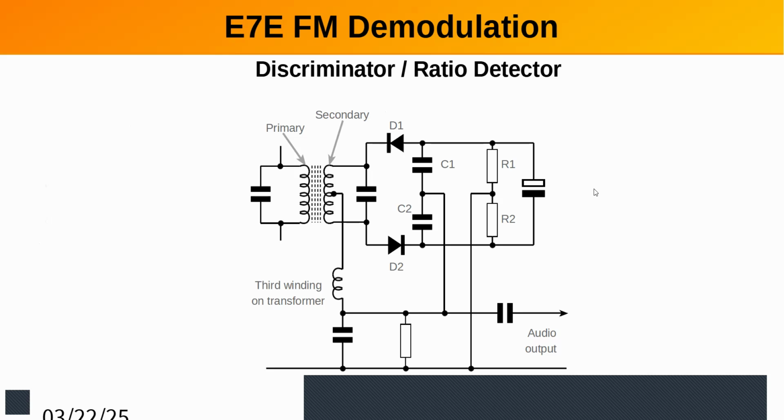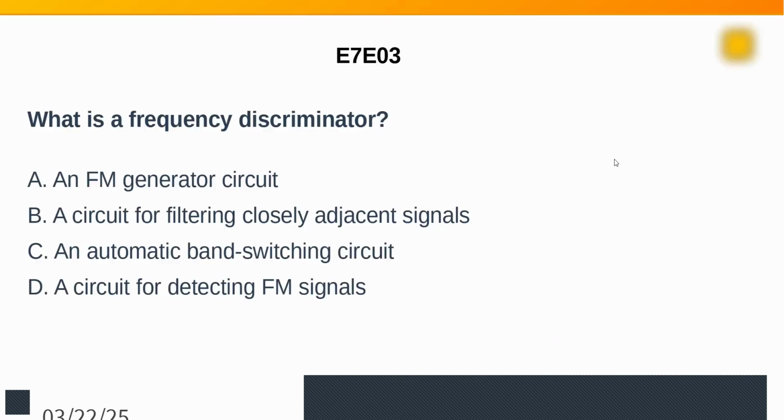The symbol for an electrolytic would have a curved element on one side, typically. It could be whoever drew it didn't fill that box in. And normally you don't see capacitors as those big, heavy blocks anyway. That could not be a big capacitor, otherwise it would shut out the signal.